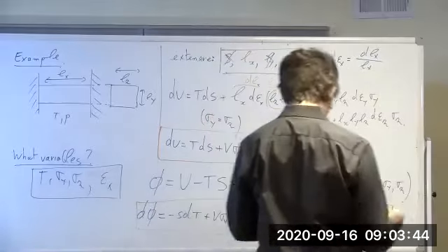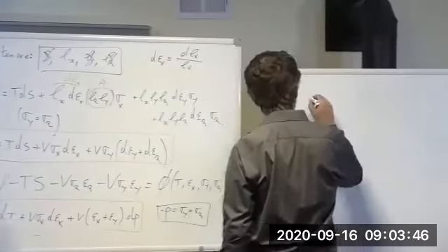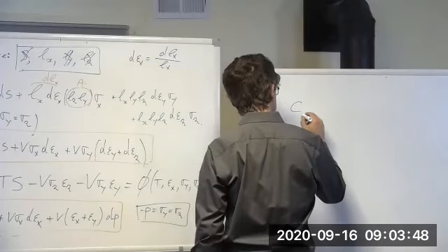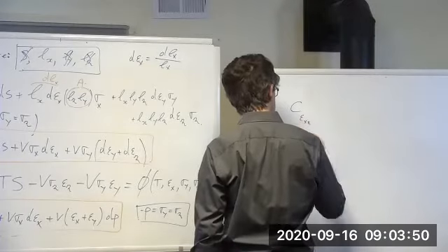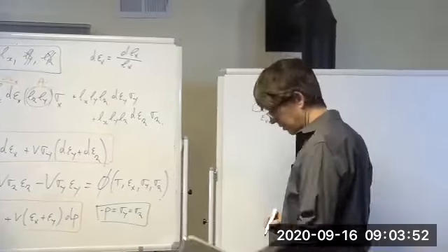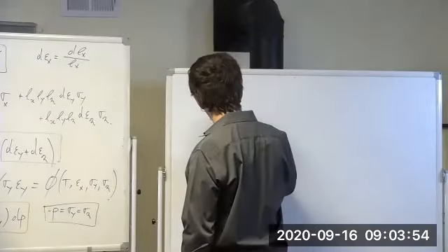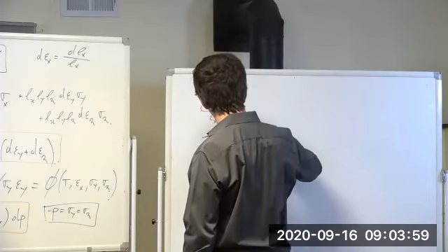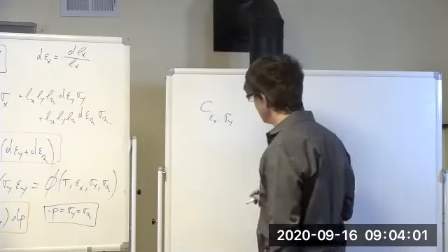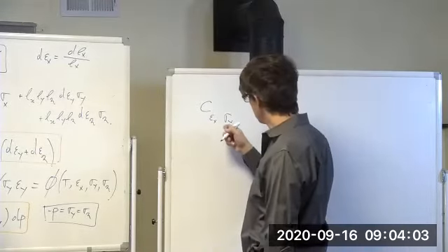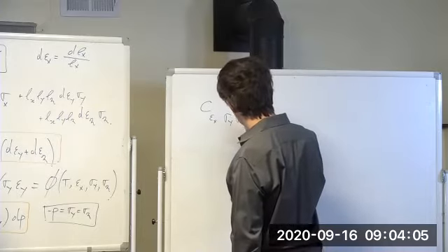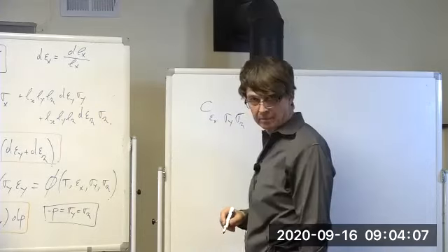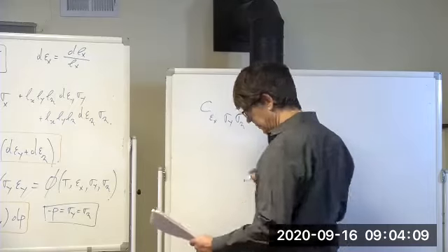But what you really need is the heat capacity under this twisted boundary condition: constant strain in the x direction, sigma yy, sorry, why did I not suddenly write two indices? So constant strain in x, constant stress in y and z. That's your relevant heat capacity.